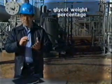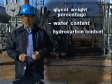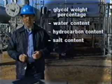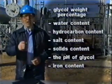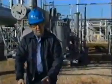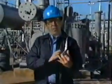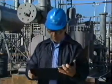It can tell you glycol weight percentage, water content, hydrocarbon content, salt content, solids content, pH of the glycol, iron content, and foaming tendencies. Let's look at a lab analysis from a typical glycol dehydration unit and see how efficiently we're operating.